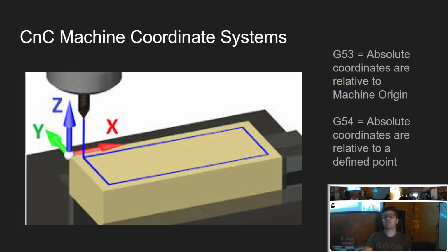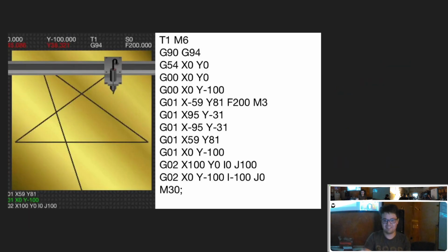That matters because when we go into Fusion 360, if I'm going to lay my piece out with the long side of my stock material pointed that way versus pointed this way, I have to set the orientation of G54 correctly in my CAM software as well. And however I want it on the machine, X is going to be to my right, Y is going to be away from me, and Z is going to be up. Does that make sense? Okay.